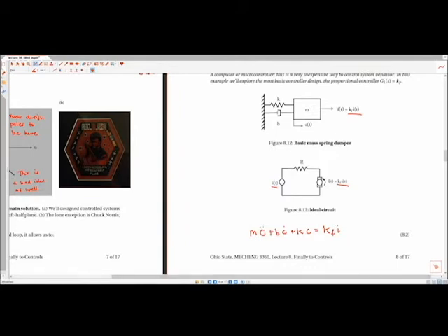We're going to almost immediately, with all these problems, jump into the frequency domain by taking the Laplace transform of this. And if we're looking at transfer functions, remember the definition of a transfer function is a Laplace transform with the assumption that all the initial conditions are equal to 0. Right? All right, so this is assuming then that the system's initially at rest. We click some sort of on button, or flip some sort of on button, right? And then we look at how does the system respond from there on.